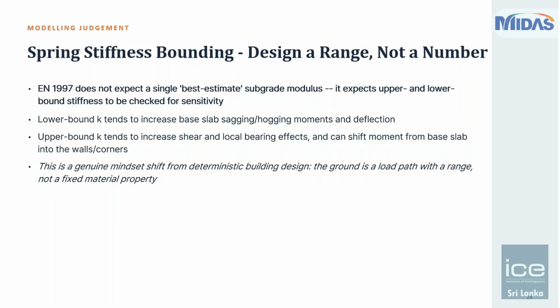for doing the critical analysis or for doing the envelope design, which covers all of the critical cases. First of all, we are making all the combinations to capture those critical effects. Along with that, the geotechnical parameter arising because of the soil spring changes will also be captured in this upper bound lower bound analysis, and it is highly suggested by the codes.